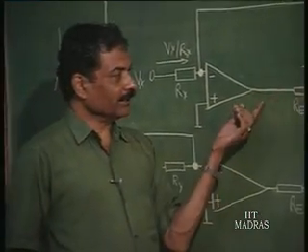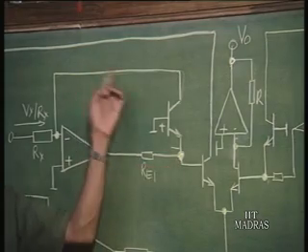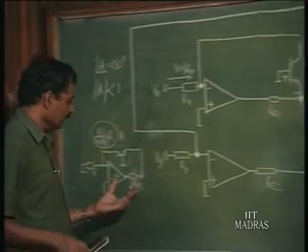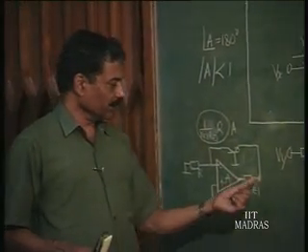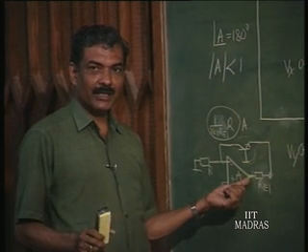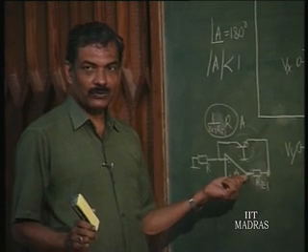Now, whether you put a resistance or not, the voltage developed is going to be always the same in order to make this current flow. So, this is something that you have to see, that in all log amplifiers they will put a resistance in series in order to make it work for the same frequency compensation arrangement as before.